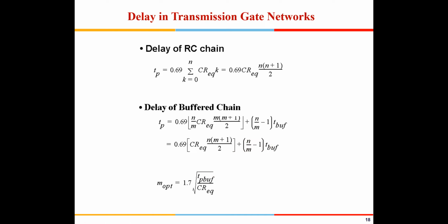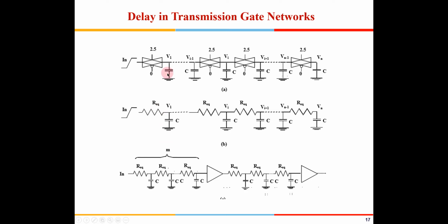So yes, you can do that at a different interval also. It's not an issue. When you implement a path, there could be differences: in one path there could be 5 pass transistors, in another path there could be only 2, right? This we are just speaking of a case where there is only a single path. There could be different paths available. Some could be critical paths, some may not be critical paths. So you might want to put some buffers in the critical path. So all those issues will be there.